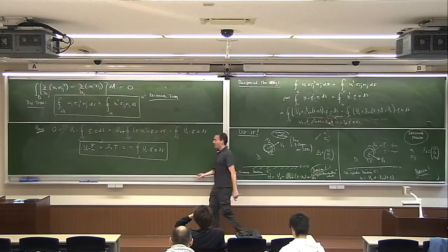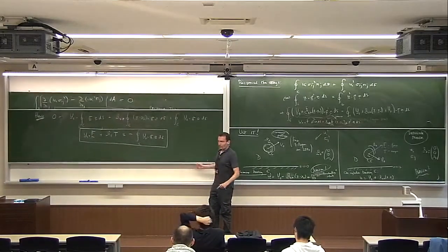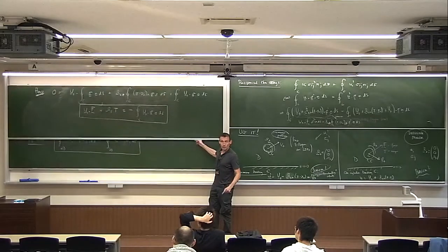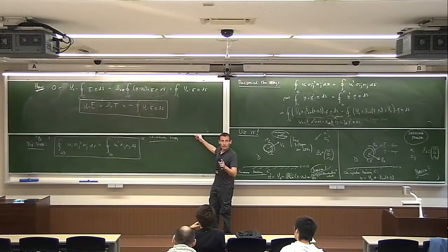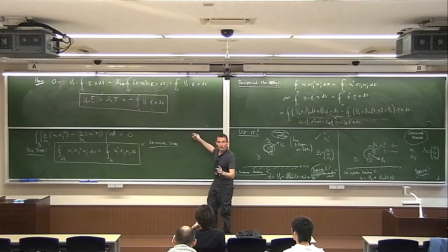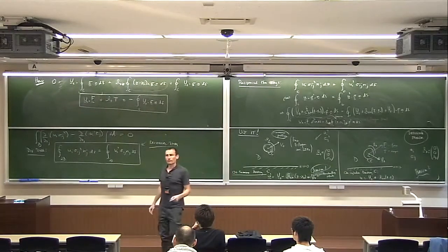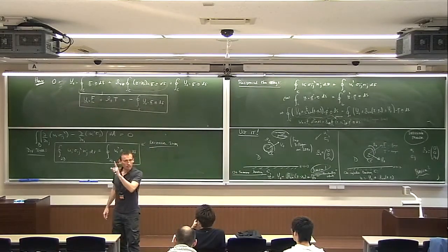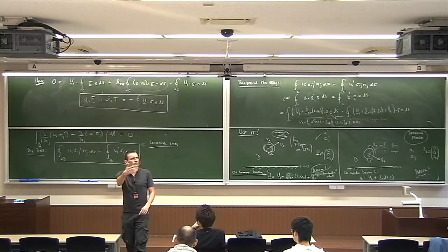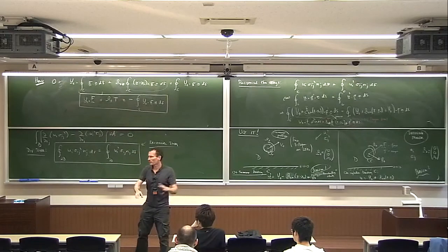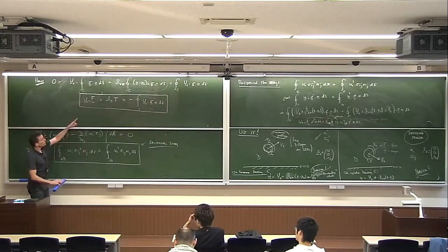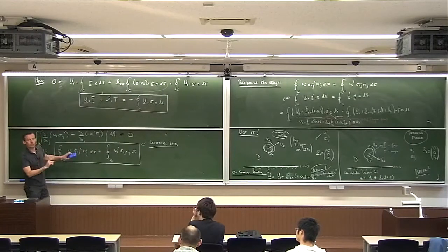But what I thought I'd do is to test our understanding of complex analysis for Stokes flows. We're going to spend 20 minutes re-deriving the Jeffrey-Onishi solution using our methods, F and G. They didn't do that. They found psi using some bipolar changes of coordinates and things like that. We're not going to do that. So let's find the solution of the dragging problem.